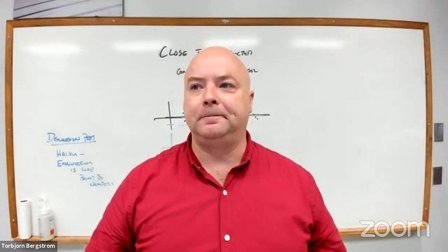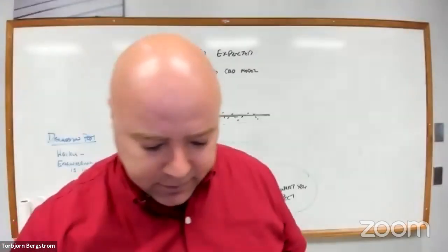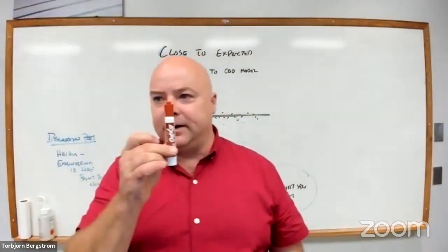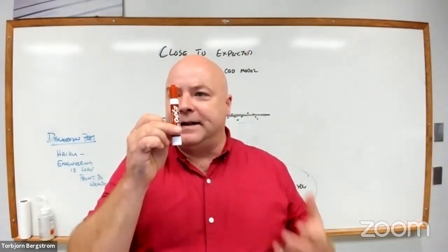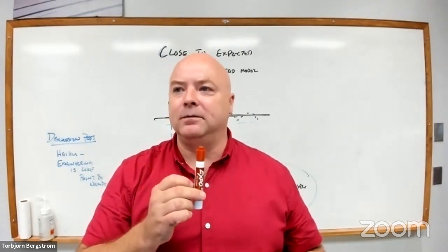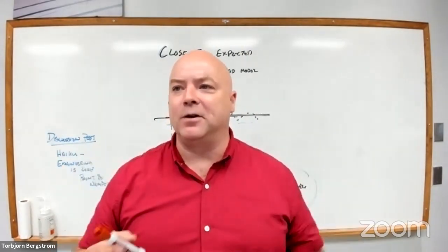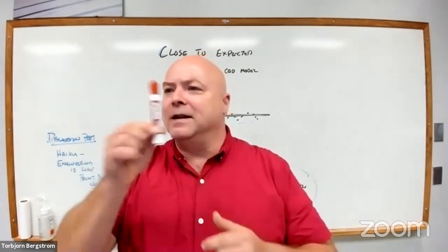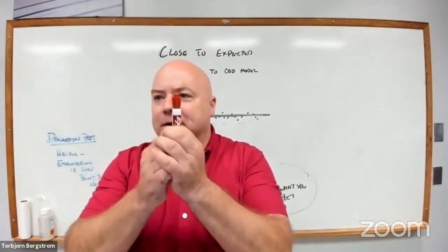except when they send me my measurement standard, and I've never had a brown one before, they say, the diameter of your measurement standard is this, plus or minus this amount. Because we know that our measurement system also has some uncertainty. And we've estimated our uncertainties, so the true value is within this range. And so now I've got some uncertainty in my measurement standard.